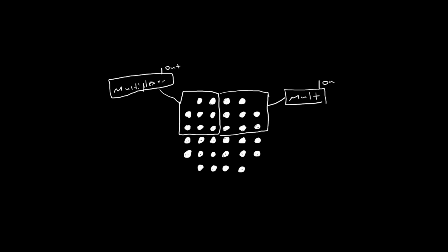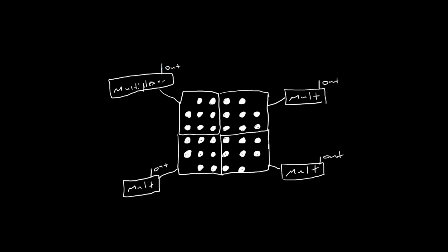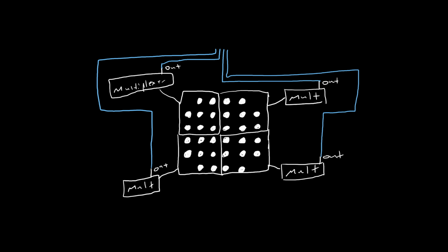To do this, 4 multiplexers will be placed on the other side of the same PCB, each selecting between 8 of the neuron matrix's pins. There's now not much space remaining on this layer, so to continue we should add another and expose the required pins. Another multiplexer will be used to select between the outputs of the first 4 multiplexers.